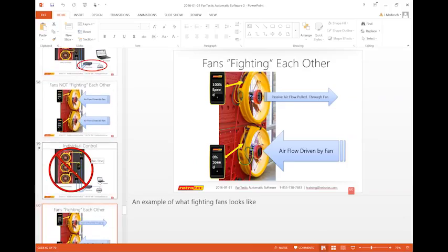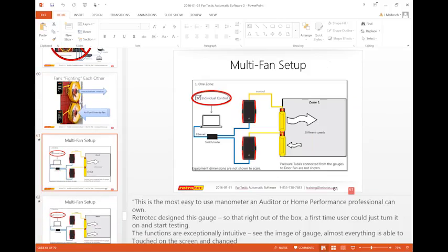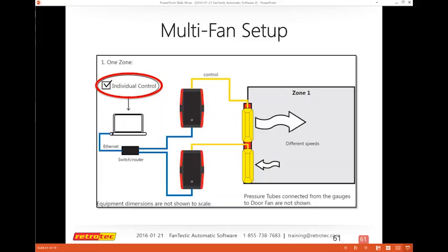So you can either do this in the software, or you can do this by wiring the fans in such a way that they're hardwired together. So when you daisy chain fans together, as I think Joe's probably about to tell you, then all those fans are common, meaning the same control signal goes to each fan. When one fan increases in speed, they all increase in speed.